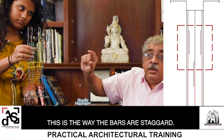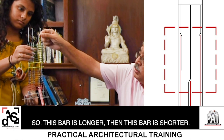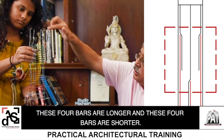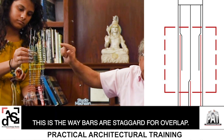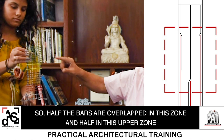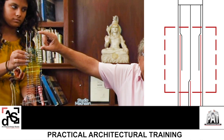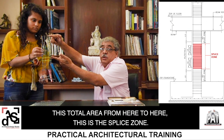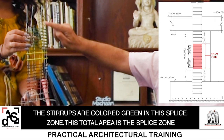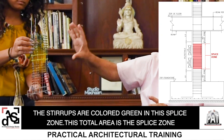This is the way bars are staggered. So this bar is longer, then this bar is shorter. These 4 bars are longer and 4 bars are shorter. This is the way bars are staggered for overlap. So half the bars are overlapped in this zone and half in this upper zone. This total area from here to here, this is the splice zone, which is the stirrups are colored green in this splice zone. This total area is the splice zone.